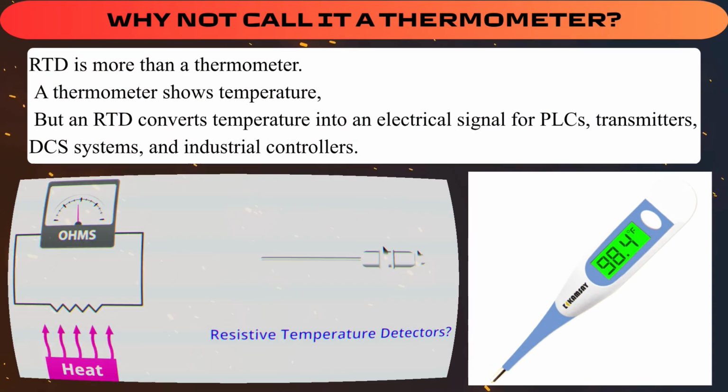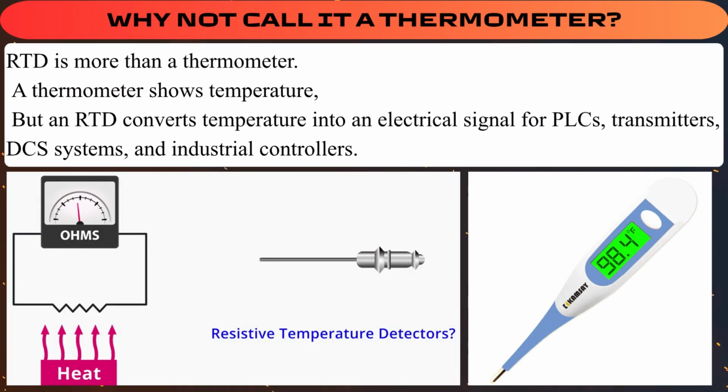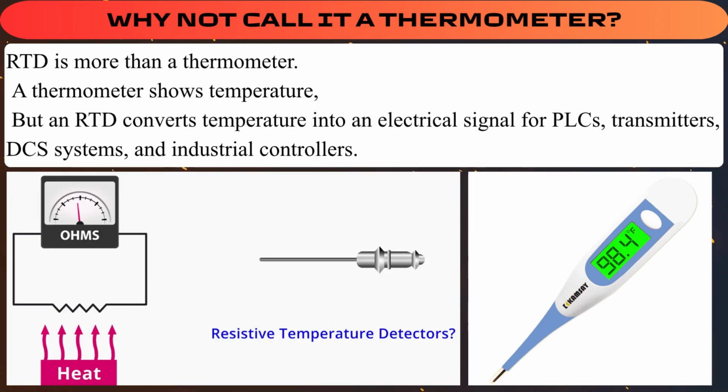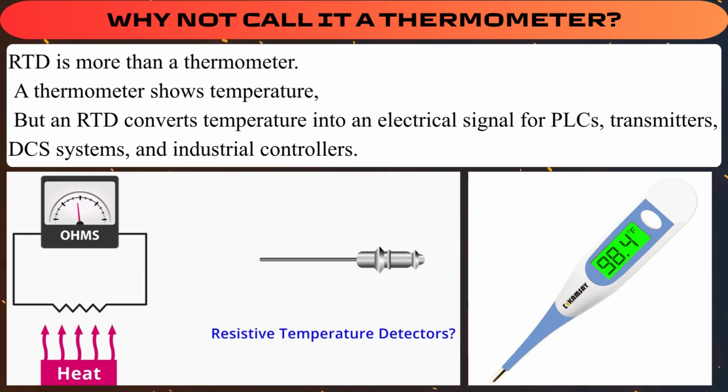Why not call it a thermometer? RTD is more than a thermometer. A thermometer shows temperature, but an RTD converts temperature into an electrical signal for PLCs, transmitters, DCS systems, and industrial controllers.